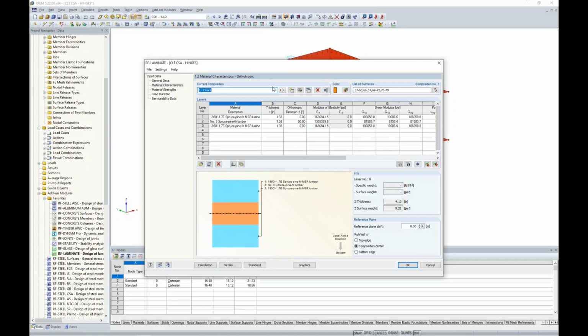So what this means, if we're looking at our walls, for example, these walls are going to take some pretty heavy gravity loads. Therefore, we want to orient the strong axes to take the gravity loads. This means the local x-axis needs to be in the vertical direction. If you do not take careful note to orient these panels in the correct direction, then you're really not getting the full strength out of the panel, and it can lead to a much too conservative design.